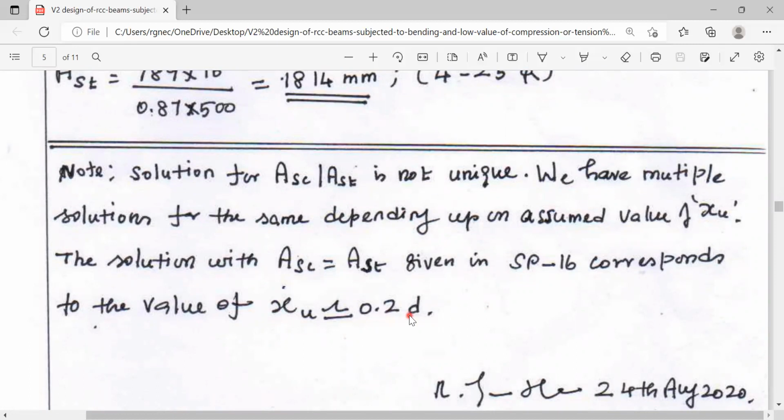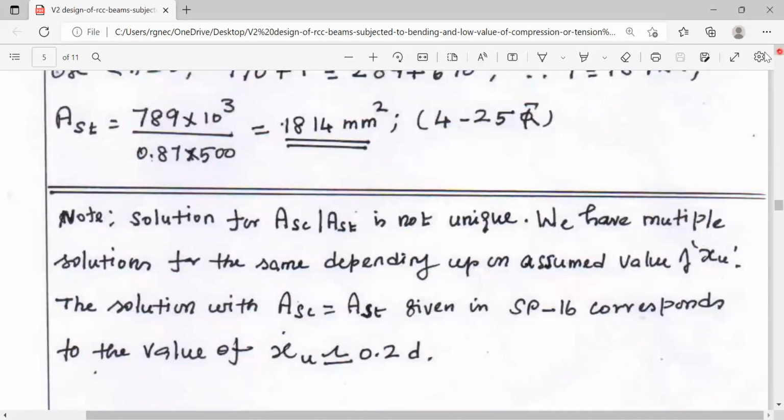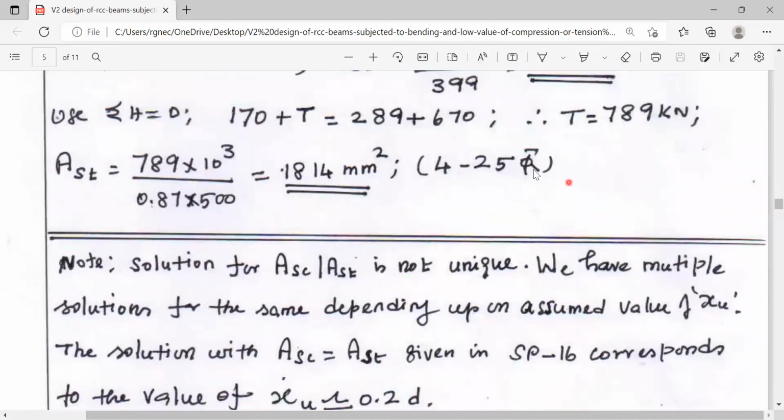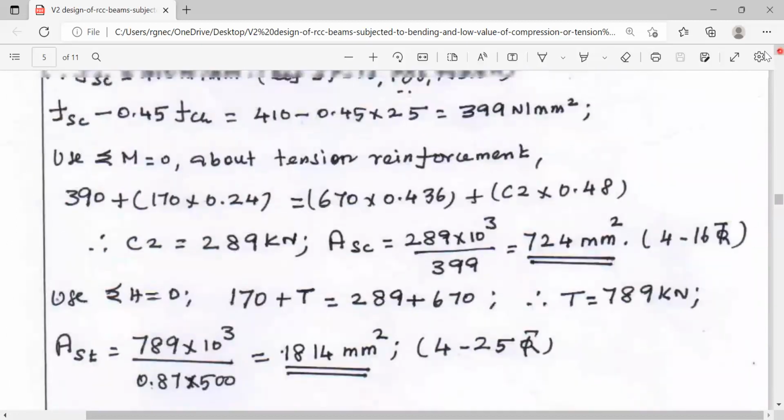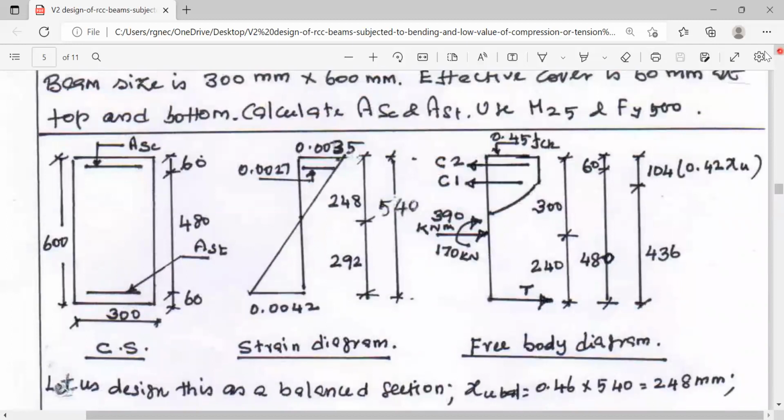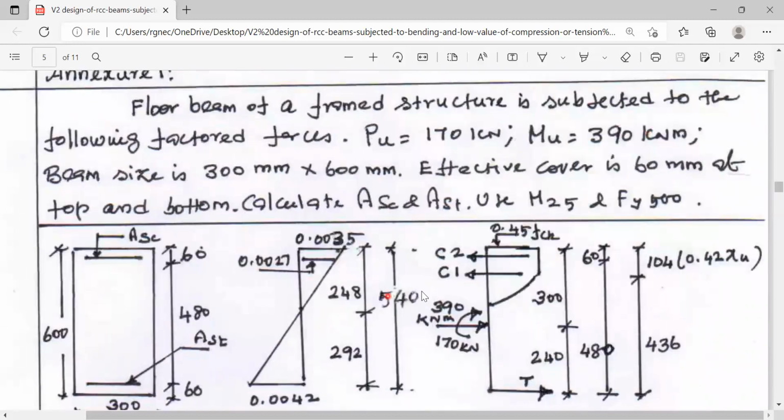And now, my request is, please follow this in practice, number one. Number two, when you are using the software for the inbuilt design, please ask for the validation from the software provider. Check whether it is in line with the equilibrium equations and compatibility equations. And in my opinion, this is not addressed in SP16 or IS 456 so far. I have already written to Professor Murthy of IIT for incorporation in revision of IS 456. You also please take it forward.